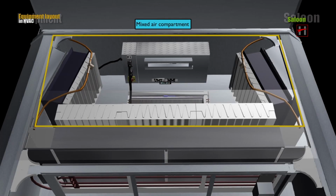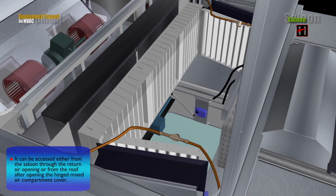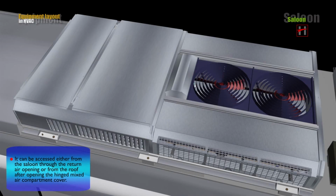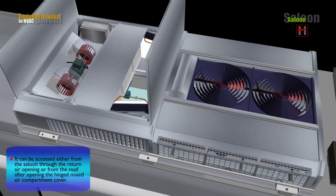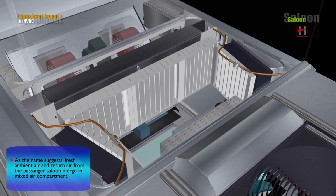The mixed air compartment is situated in the center of the HVAC unit. It can be accessed either from the saloon through the return air opening or from the roof after opening the hinged mixed air compartment cover. As the name suggests, the fresh ambient air and the return air from the passenger saloon merge in the mixed air compartment. The mixed air is subsequently filtered, cooled or heated before it is discharged into the supply air duct of the passenger saloon.